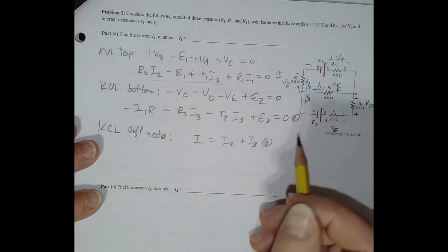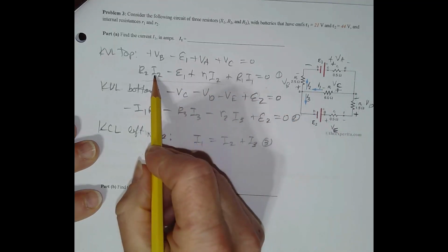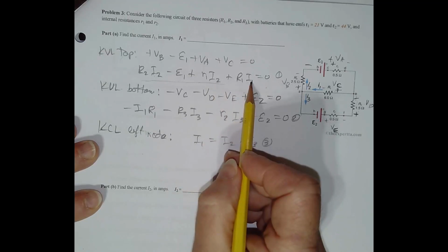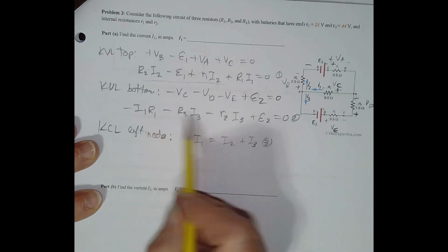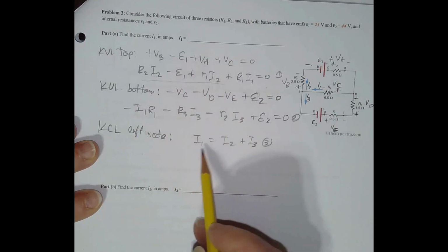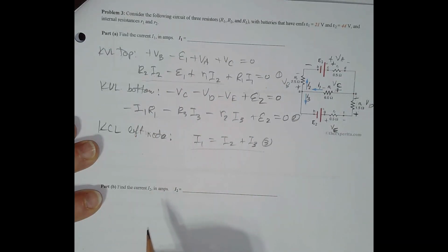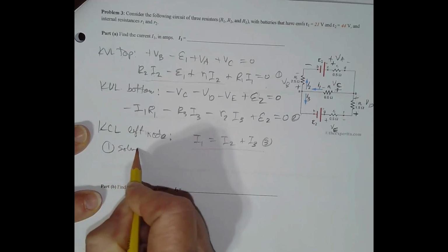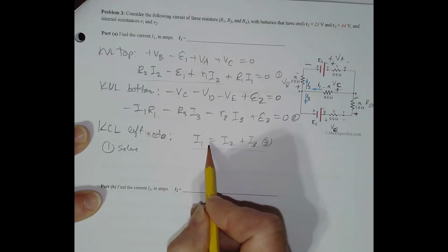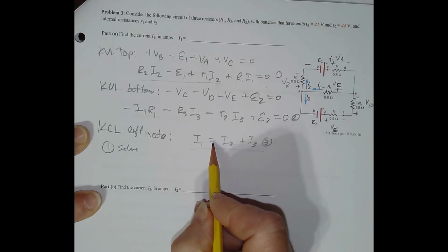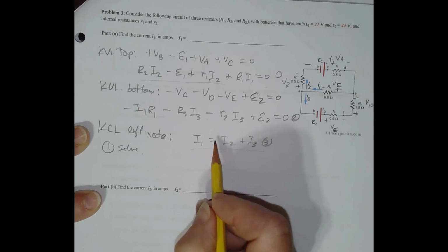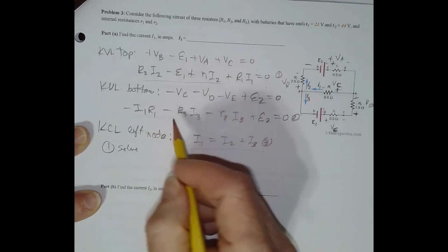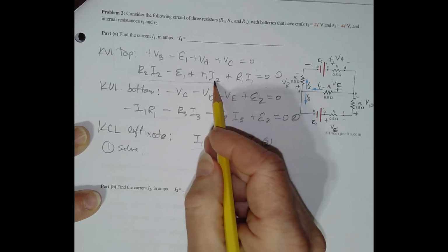Okay, so what do we have? The first equation has I2 and I1 in it. Second equation has I3 and I1 in it, and then we'll assume the other things are known. And this one has all of them in it. So when you have something like these circuits that we've been doing, 2-loop circuits quite a bit, probably the easiest is to take one and solve for the one that's in common between them. Yeah, so I1. So solve for the other one in terms of that one.